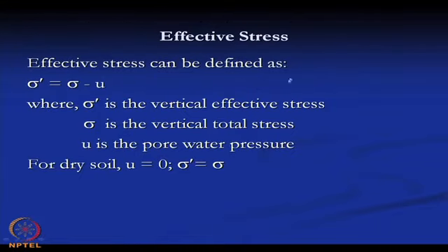So, the next concept is the effective stress concept. Now, what is effective stress? Effective stress can be defined as the total stress minus the pore water pressure, where sigma dash is the vertical effective stress, sigma is the vertical total stress, and u is the pore water pressure.